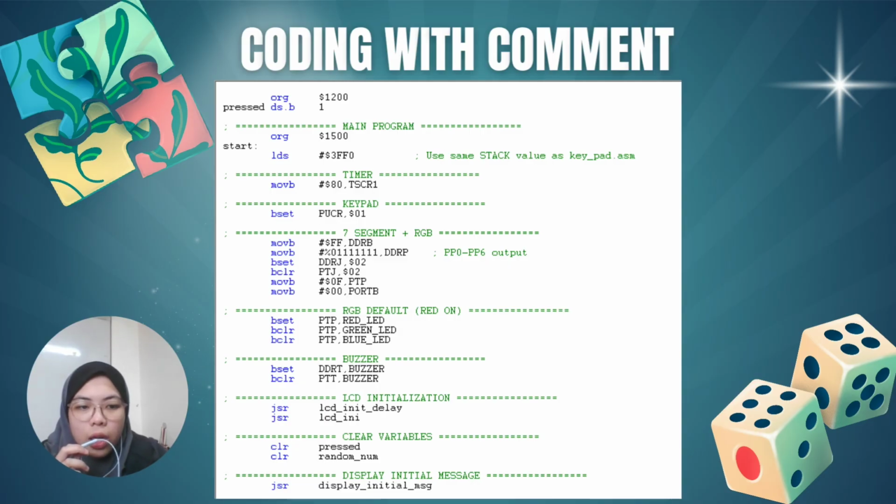The LCD is initialized to prepare it for displaying messages. All variables are cleared to avoid undefined values. An initial message is displayed on the LCD to greet the user. This part of the code initializes all hardware components such as the timer, keypad, display, LEDs, buzzer, and LCD. It ensures the system starts in a safe and known state before executing the main program.